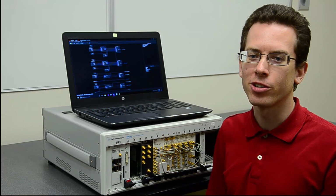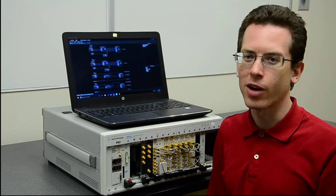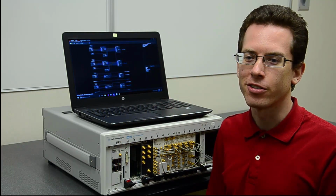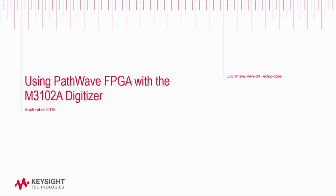In the following tutorial, we will be using the graphical programming environment PathWave FPGA, which runs on your laptop or desktop PC to configure the FPGA in the module. In this tutorial, I will demonstrate how to create a PathWave FPGA project for the M3102A BSP. To get started, launch PathWave FPGA from the Start menu and select File, New Hardware Project.